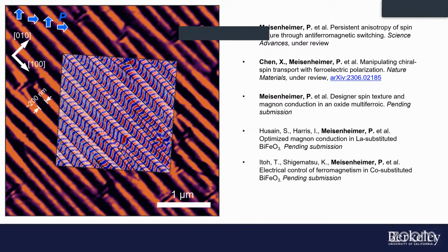Yeah, people definitely try to do it. There's a lot of work that's gone into photoferroelectric effects in BFO because the band gap's pretty small. It's 2.5. So it's not semiconductor small, but small for an oxide. People have done it with terahertz pulsed stuff to try to actually switch it, but I don't know of any work that's been done outside of synchrotron experiments.